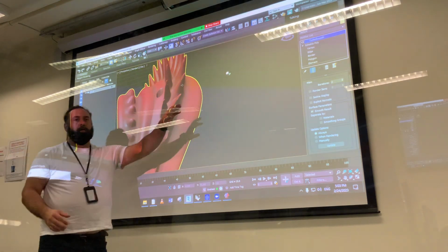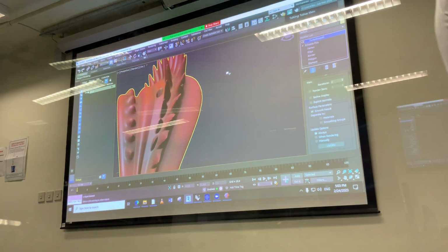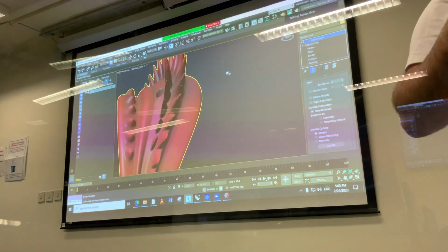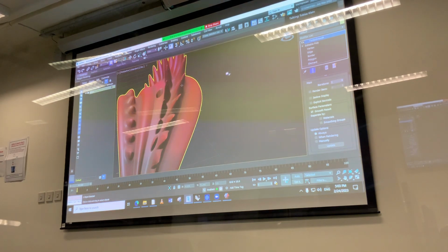So we use the curvature in Rhino to basically create the faces. And all the options that you do in topological modeling are perpendicular away to the curvature of the ring. So you see then these global shapes here, they're basically following the curvature. And so when you set your curve smart, the topological modeling afterwards, whether it's spikes or bridges or other things, they always will follow. And that's kind of making this really smart.